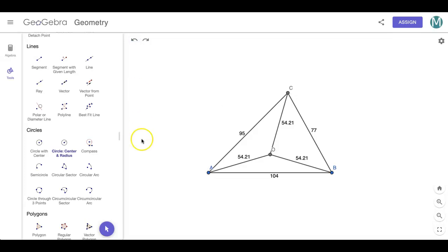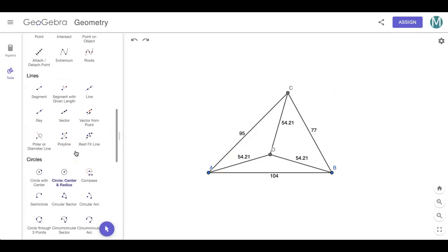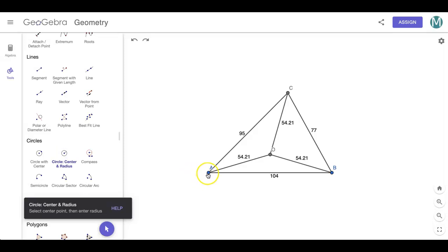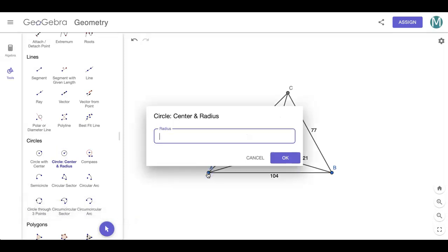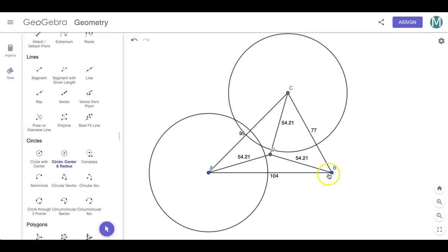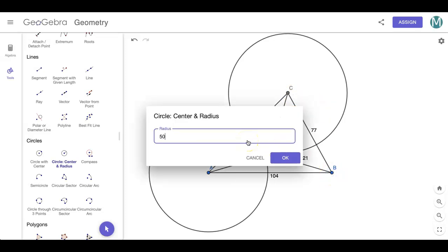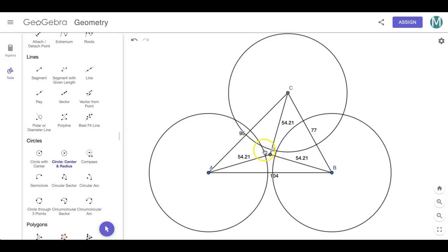Let's go back, and now I'm going to try the lamp radii. This is my figure. Let's try 50 meters, the first lamp, second lamp, and third lamp, each 50. As you see, this region is not illuminated. This is a safety concern, so of course we are not going to pick this one. It is cheaper, but we cannot use it.